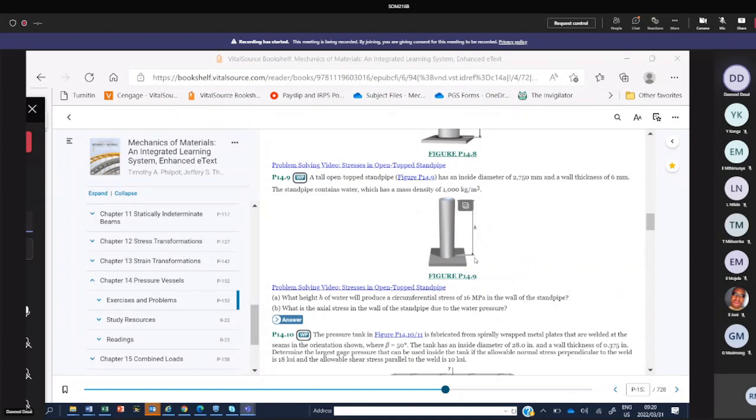Okay, guys, we're running out of time now. This height here. Question is, where is the pressure? The pressure is not given. You have to calculate it. The pressure can be calculated by the formula used in fluid mechanics called rho g h. I hope you're writing, eh? Rho is density. g is gravitational acceleration, 9.81. And h is the height of the fluid in meters. Now you can calculate what the pressure is here.